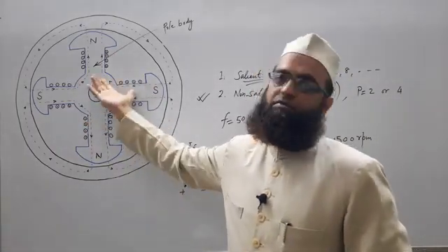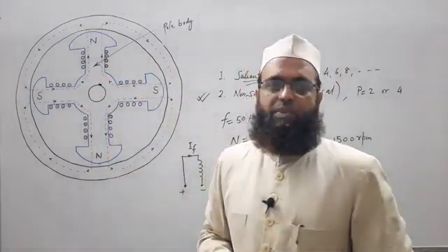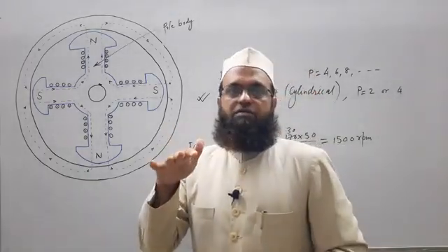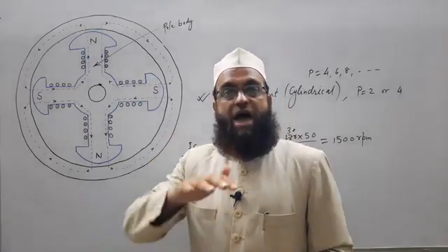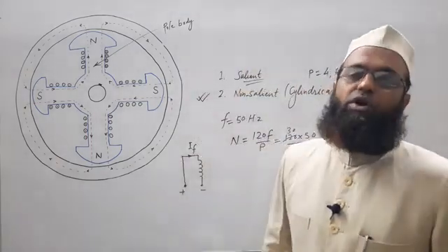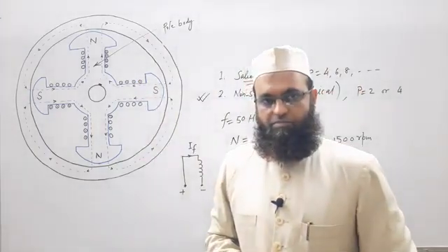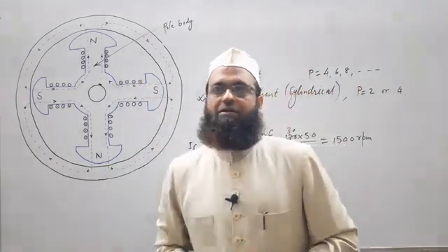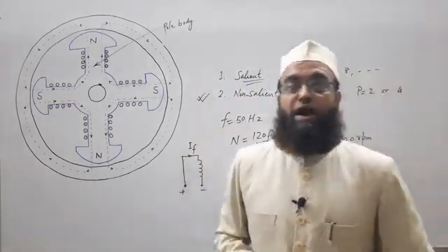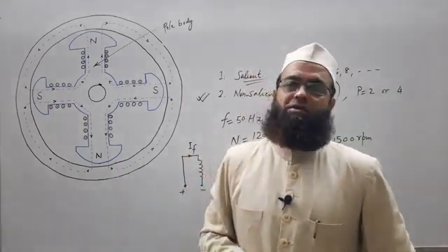So the corresponding field is there. Once the rotor is being rotated, the windings are also being rotated, and you have provided supply, though DC in nature, but once it is rotating, the conductors placed on the stator will experience varying flux with time. So as per Faraday's law of electromagnetic induction, we know that EMF will be induced in the stator windings. Good, but the generated EMF so induced in a stator winding is required to be sinusoidal in nature. This is our requirement.